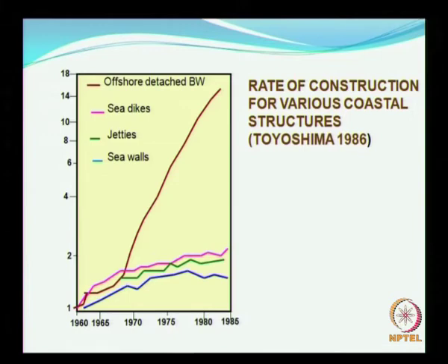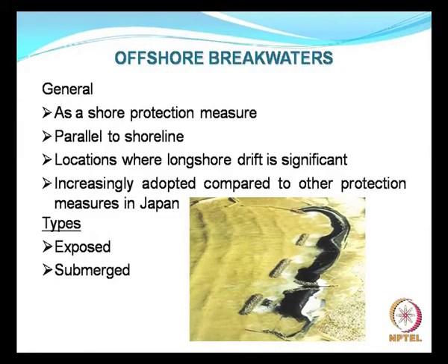So let us see what offshore detached breakwaters are. You have a picture down below. In general, it is used as a shore protection measure. The structure is parallel to the shoreline. Again, similar to a groin field, it should be adopted at locations where you have longshore sediment transport which is quite significant. This is, as I said earlier, increasingly adopted compared to other protection measures, particularly in Japan.